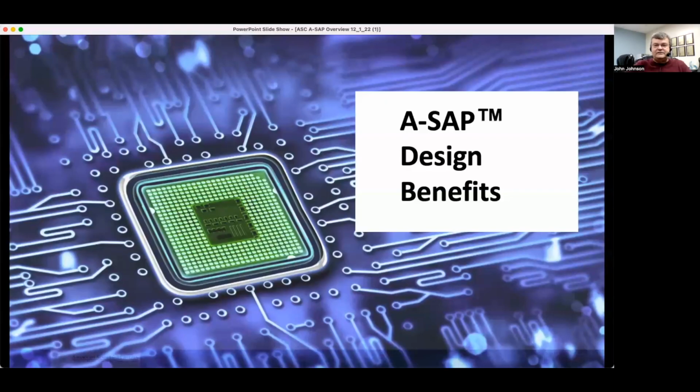There are some things you have to watch out for in a design, and because you can do the ultra fine lines and spaces, a designer has a lot of things in their toolkit today. You have via in pad plated over, you have microvias, you have stacked microvias, and all these different structures.